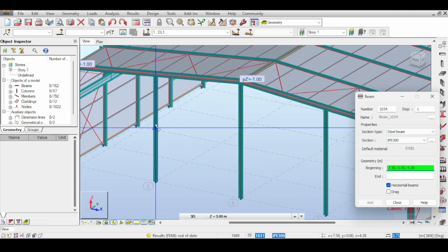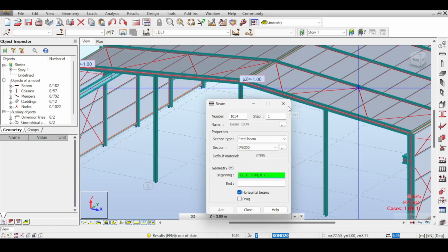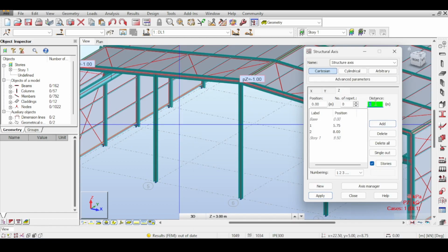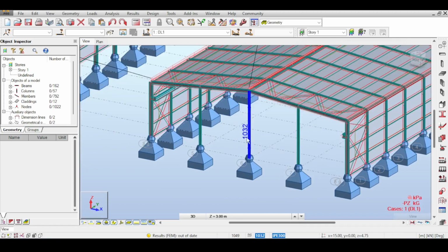And I need some heights. Okay, I need a truck, right? Trucks usually go through bridges of 5 meter height. So define an axis of 5. That's for the trucks, basically. Wait, what? No, I mean 5 position. And for humans, I'm going to put a door of, I don't know, 2 meters is enough. I think 2 meters is enough, or 2.2 if I want. 2.2. I'll apply, and now I have both z axes ready to use.